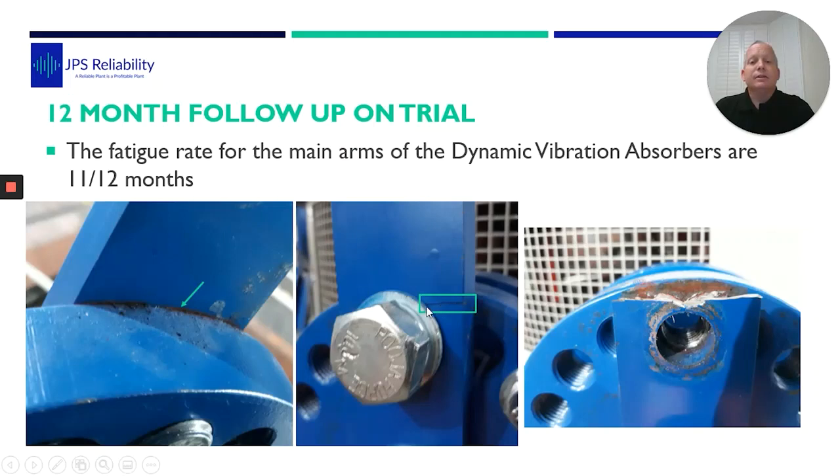If you look here, a little crack, and we can see signs of fretting. Now the motor was still running when we went on site. This one wasn't working, but it stood dead still. Tethers, safety tethers were still there, but nothing was wrong with it. And then in hindsight, you think about it, we designed it to vibrate at a certain frequency. As soon as that bar cracked, the whole dynamics, the physics of that bar changed. So hence, it stopped vibrating. So literally just stood there. You could grab that and just pull it off.